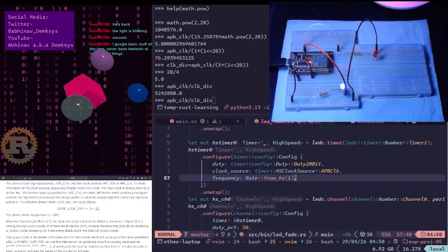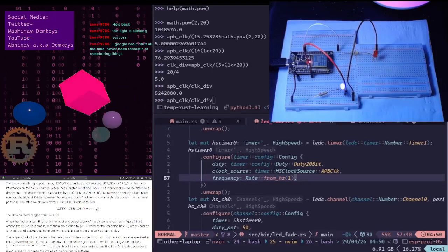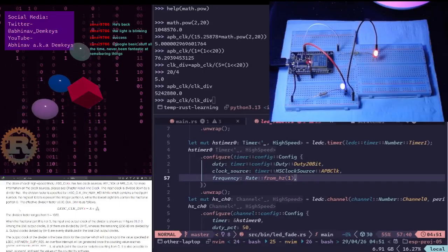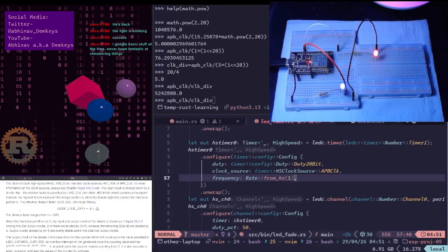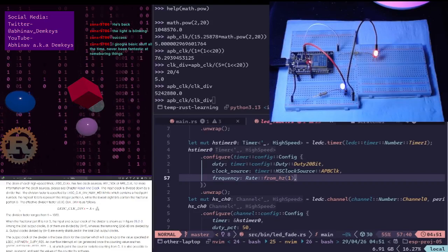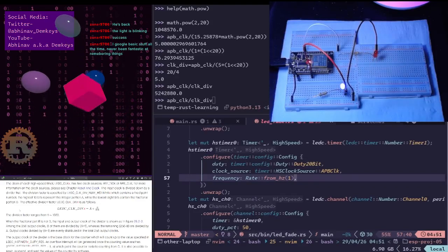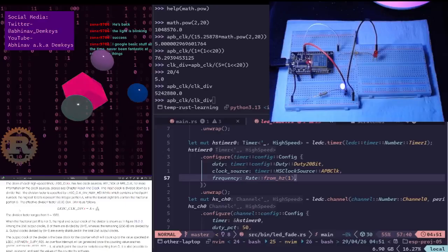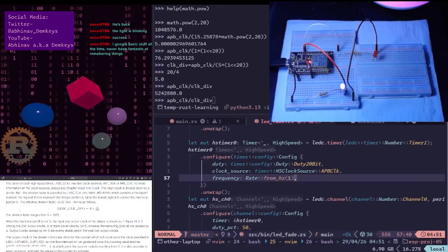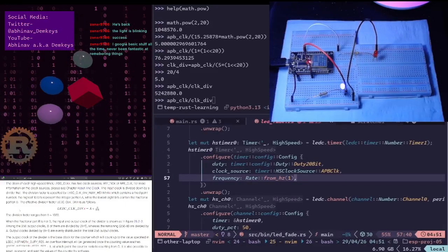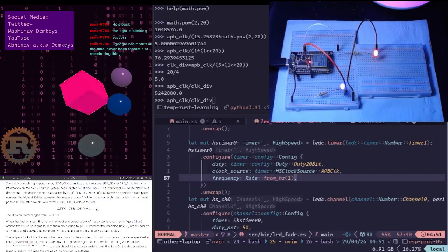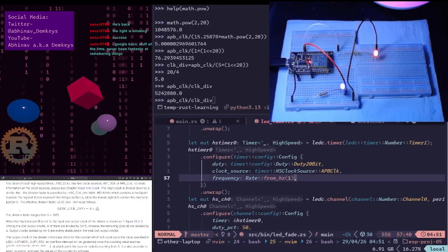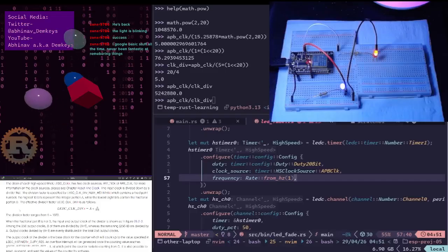If your divider is set to n, the hardware takes the high-speed APB clock. An internal register counts APB clock cycles. When the count reaches n, a single tick is issued to the PWM counter, and the internal divider register resets to zero.